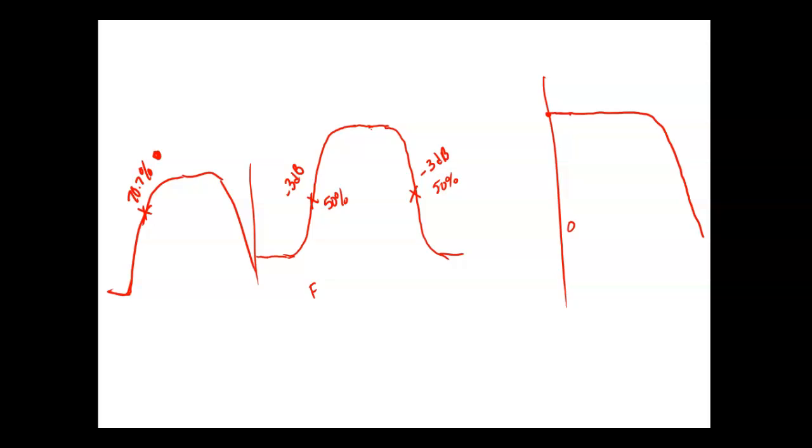It's pretty neat. Current is hard to measure. To truly measure current, we have to break the circuit and make the current flow through the meter. Power is hard to measure because we always have to measure two things. Voltage we can measure with an oscilloscope, with meters, all kinds of stuff. So it's nice to be able to relate power to voltage, and we showed y'all that. I have the power, I have the voltage at 70.7%, and it came up with 50% power.